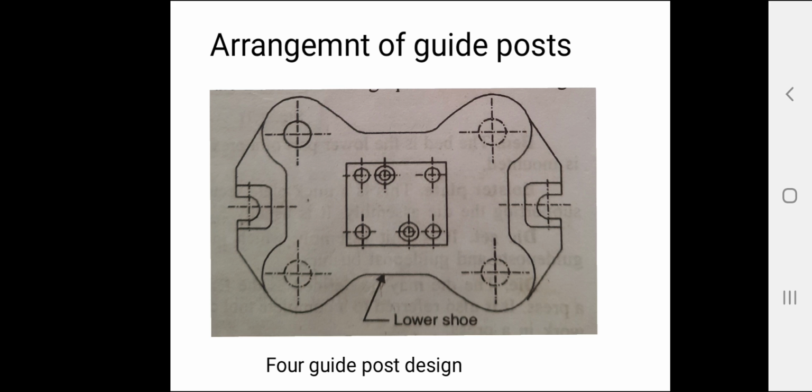So this is about the arrangement of guide posts. We discussed back post design, axial post design, diagonal post design and 4 post design. So there are various arrangements of guide posts. The guide post is used for guiding and locating.